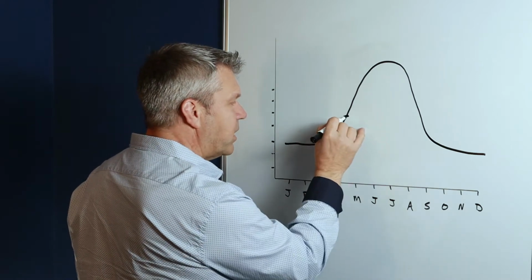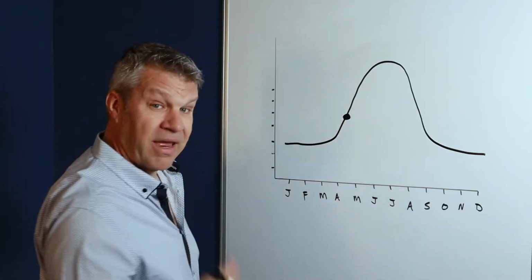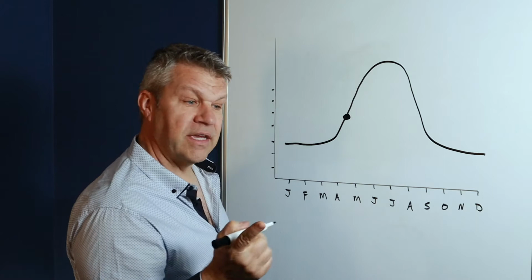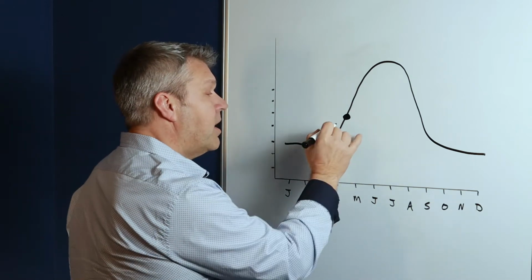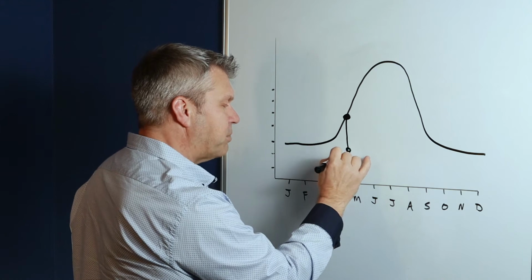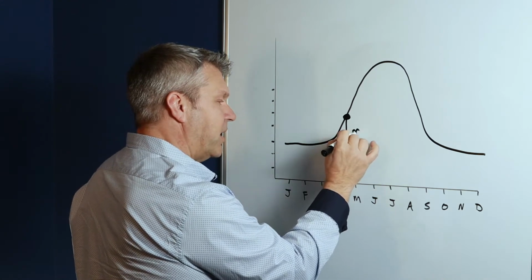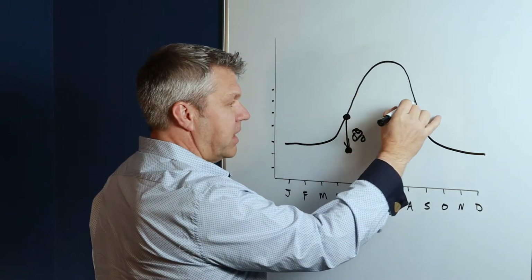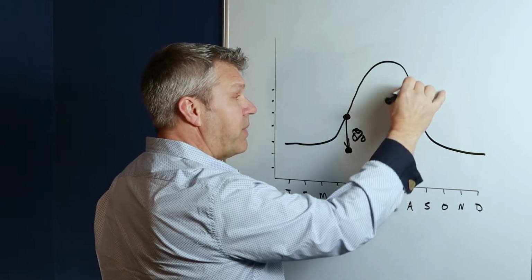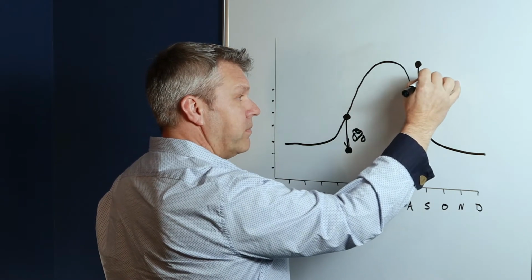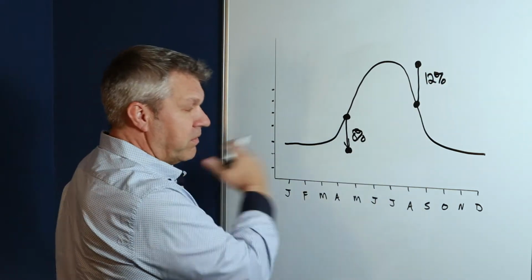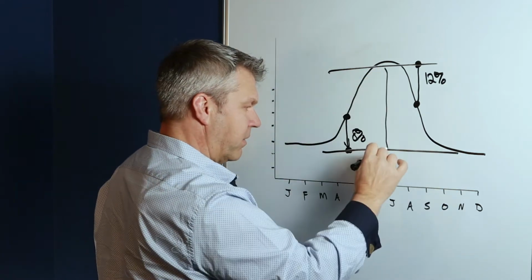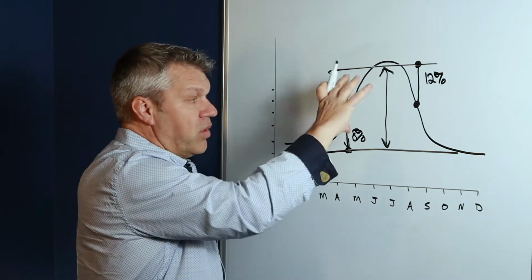If you look at this, here's where we were for May. This is our consumption for May this previous year, and we're going to compare it to the year before. After you normalize for weather, you're going to see that the variables cause problems in your bills. Maybe this bill went down for no explained reason. It went down 8%. We don't know why. That's the variable interference. And as you go through this month by month, let's just say August, for some reason your power consumption went up 12%. We don't know why. We've normalized everything we can. You have a 20% delta right here. And so you know this is real.